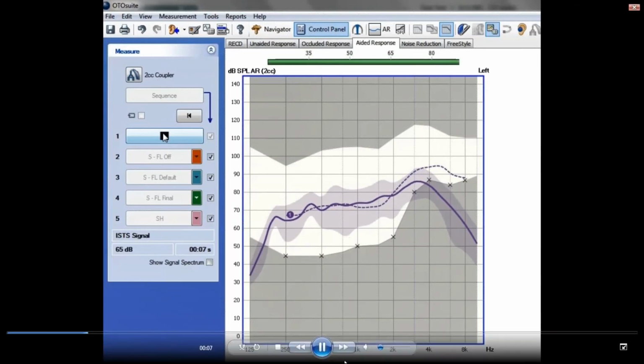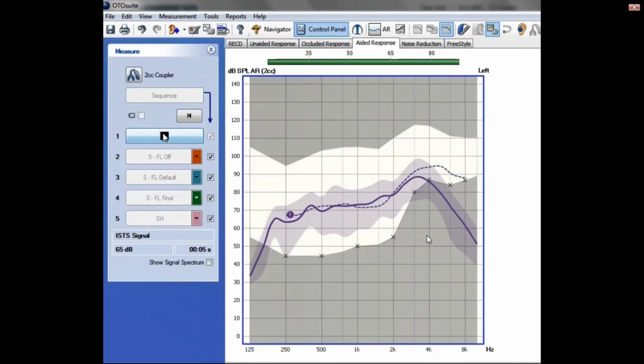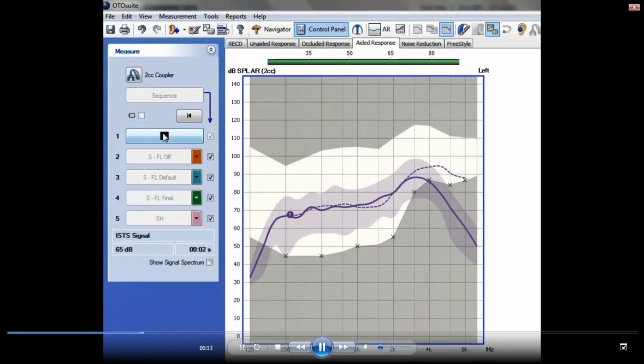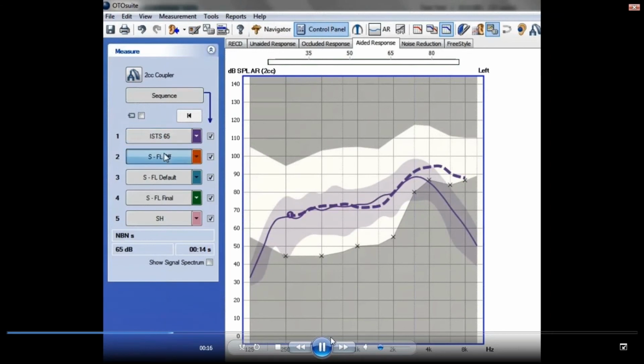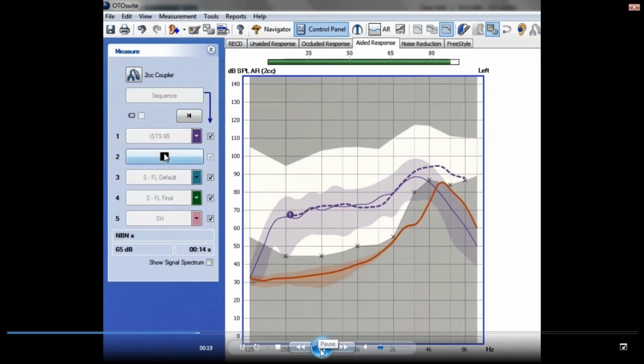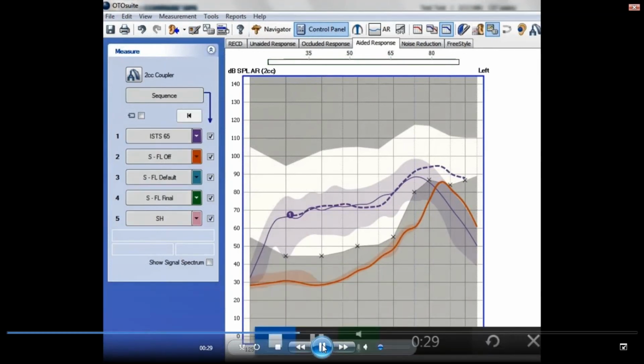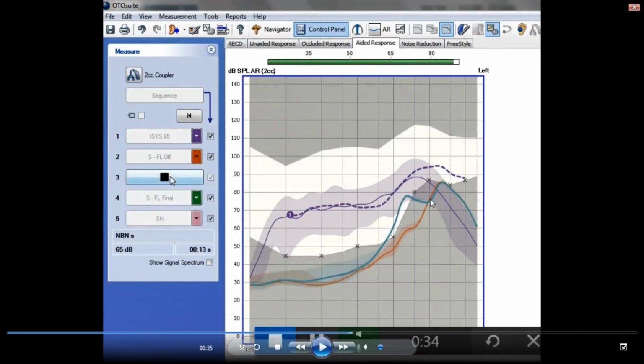And after that, I will activate my S in isolation with no frequency lowering turned on. And in this case, not only am I not in that MAOF zone, which is right here, I'm not quite audible. My peak is in the MAOF, but I'm not quite audible. So I activated frequency transposition. And what you'll see is that this specific setup actually maintained some of the higher frequency signal, the S, and then also reproduced it down here.